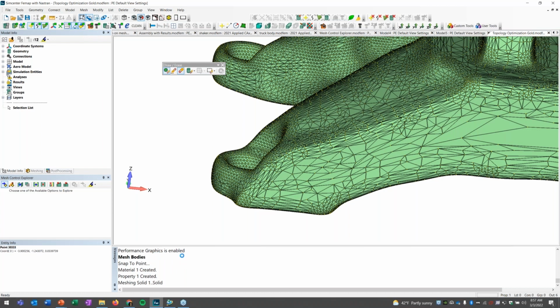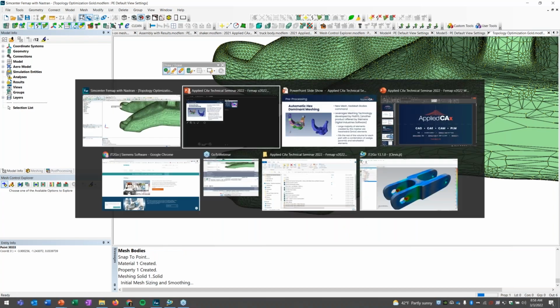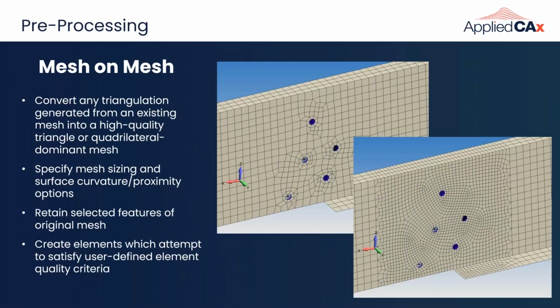One of the things that I wanted to compare was the body mesher to the previous popular approach for TET meshing, which is geometry preparation. Geometry preparation would identify, based on your target mesh size, all sorts of small entities, slivers, and small surfaces that you wanted to get rid of. So it's still a really useful tool, but I wanted to see how the two compared against each other. Now, while we let this guy churn over here, I'll show you some of the results.